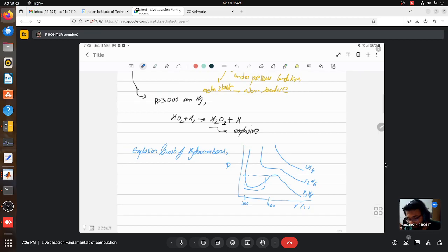So hydrocarbon fuels exhibit single and two-stage auto-ignition processes like what you see there. For higher order alkanes, when temperature is around 300 to 400 degrees centigrade, the reaction zones often appear accompanied by a faint blue emission. Only a small fraction of the reactants react with a very small temperature rise. This is what you refer to as cool flames.